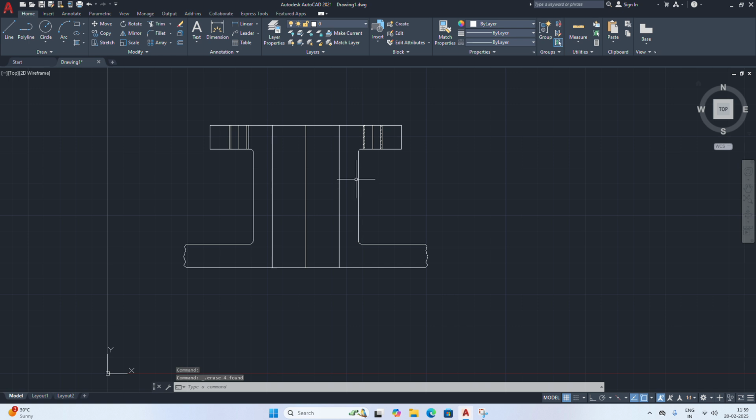Okay, and this line we will draw from here to this portion, and this portion we will trim, this one. That's all. And here we have a 33 mm small cavity, the gap there, so that we can place that bush. So this is 33 mm, which means offset through 16.5, offset through 16.5, this center line on either side.